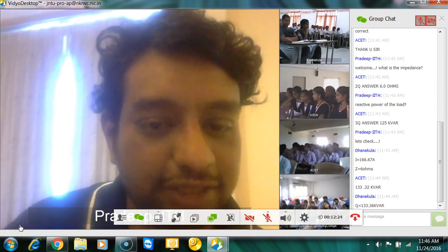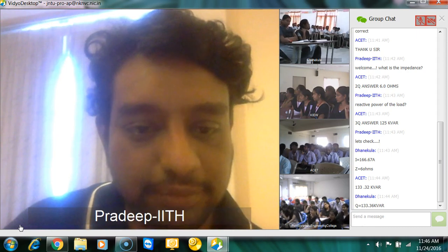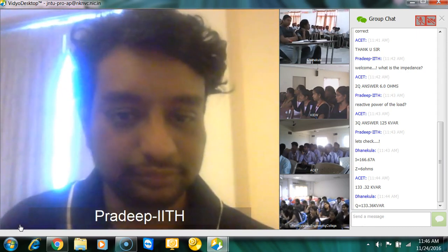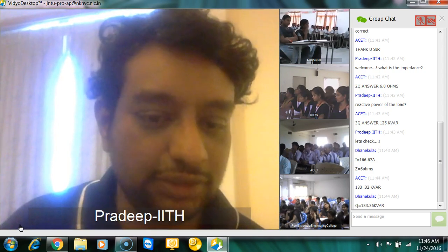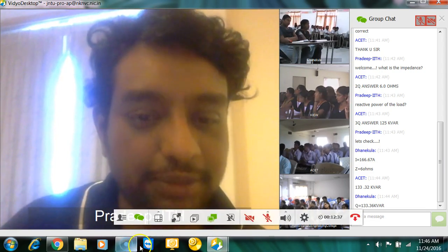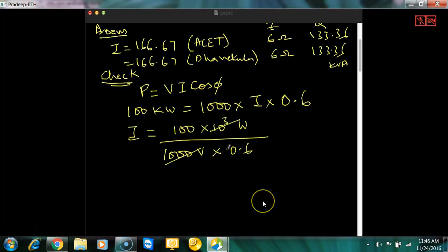Into 10 to the power of 3 watts, divided by 1000 volts into 0.6. Okay, so these two will cancel each other. So 100 by 0.6, that is 166.67 amperes. Okay, so I got the current.